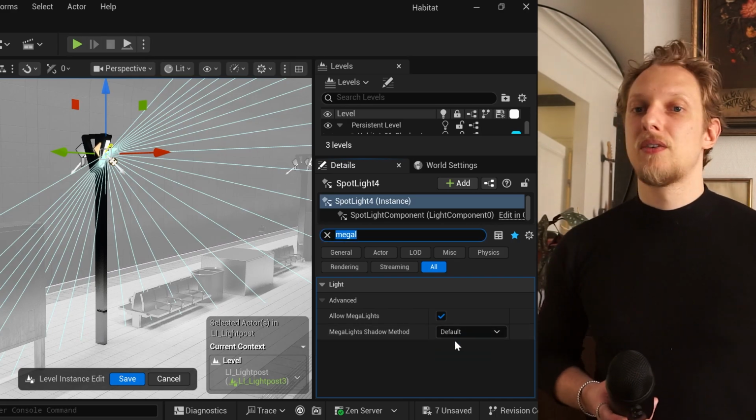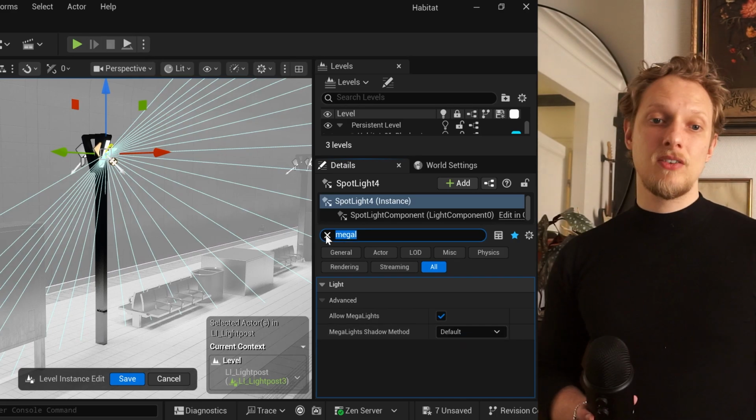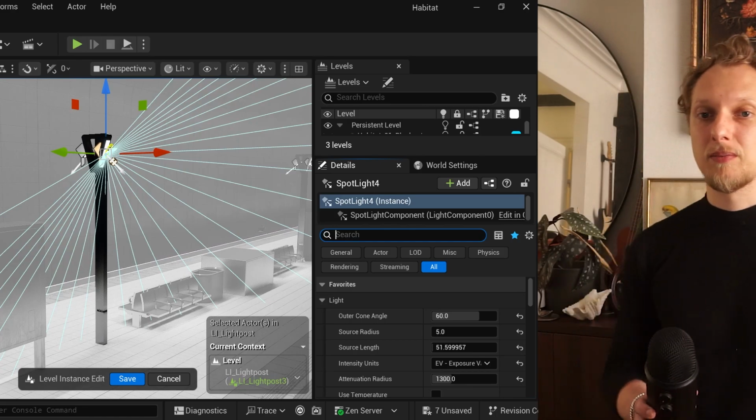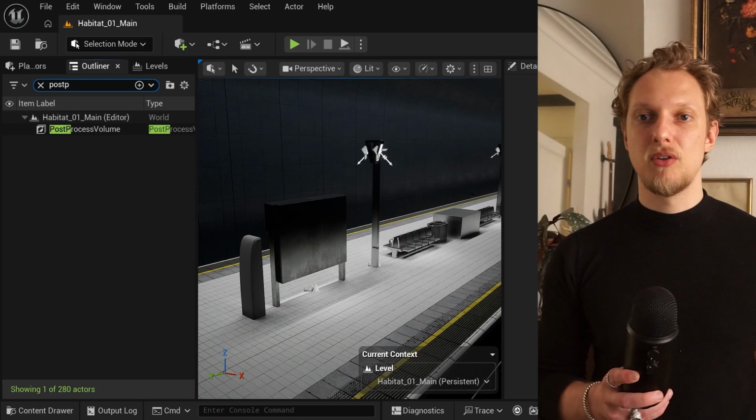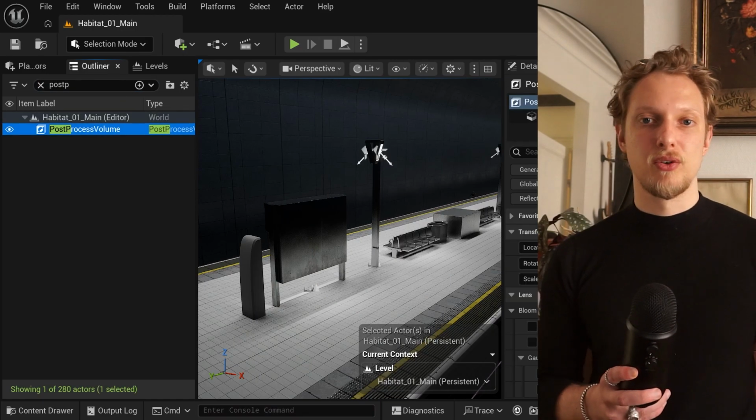It tends to add a significant per light CPU, memory, and GPU cost to generate shadow depth maps. Preserve it for lights where the ray tracing scene's simplified geometry causes visible shadow artifacts, and precise, hard-edged shadows from Nanite are pretty critical. Also, you can enable or disable MegaLights per zone using post-process volumes.